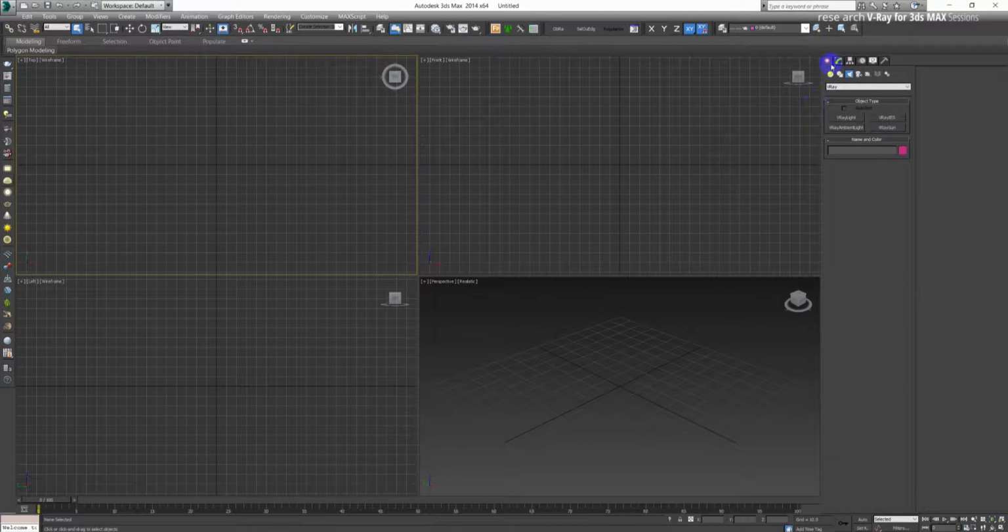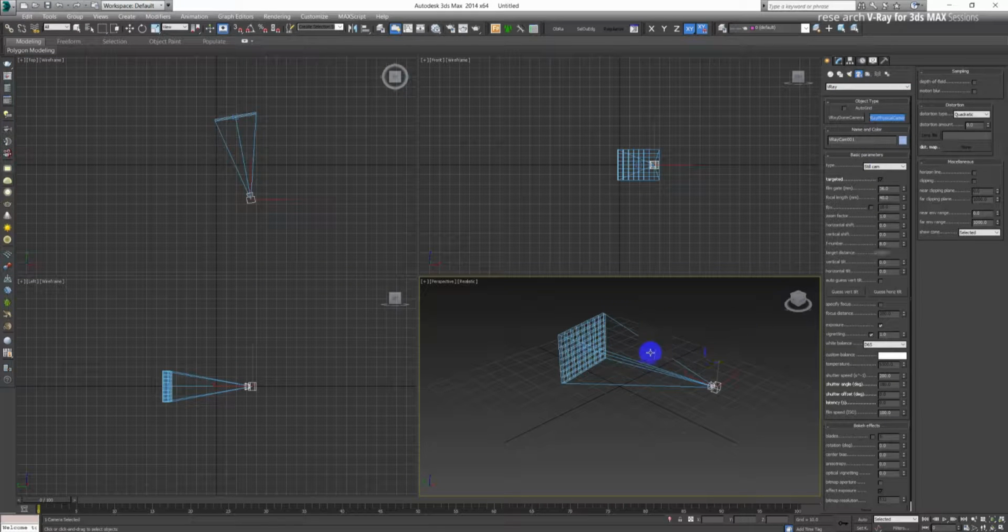Another thing is to go again here. You have pretty much the same representation as here. It's just through the buttons and through the rollouts. So here is again the Create tab, and here you can find the same V-Ray elements as we had there, and the same applies when you go to lights. You have V-Ray lights. Besides photometric and standard, we have V-Ray camera, dome, and physical one. So this is pretty much where it is. So you simply can select it, drag it out in a scene, and you have it there.